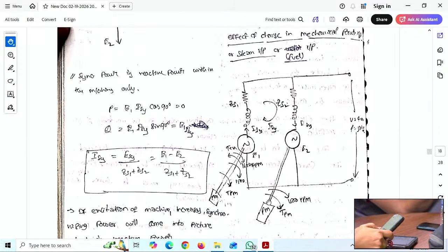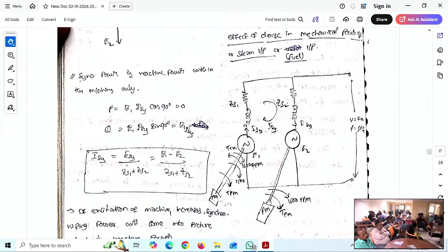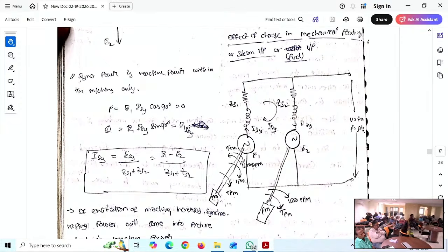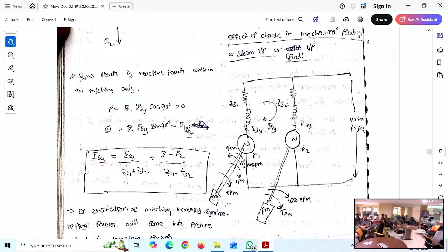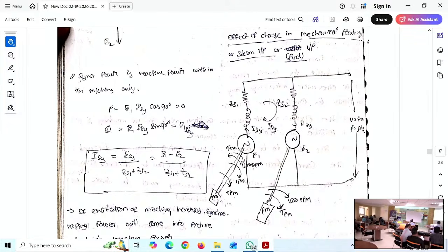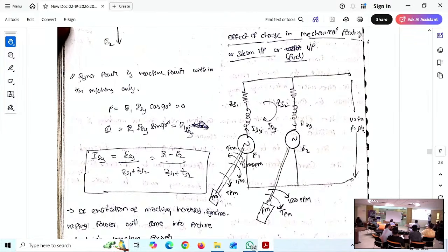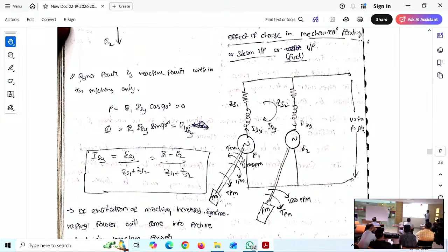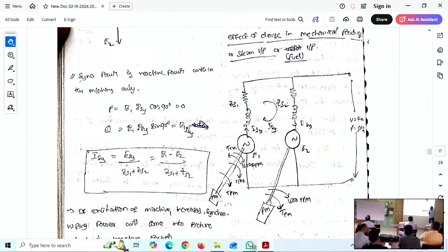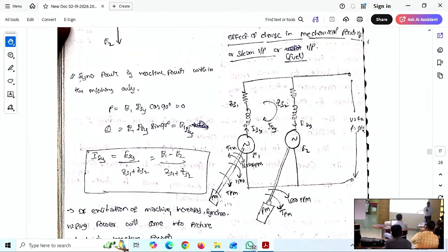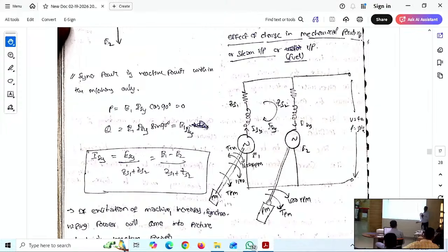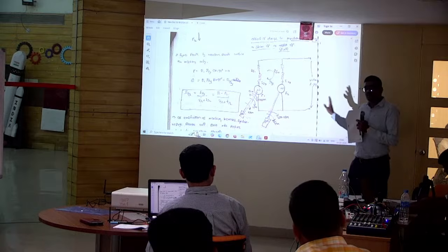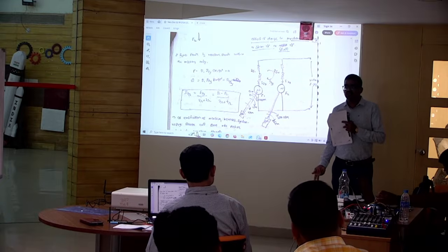This we understood, I think. In the first case, when prime mover input is constant, flux is changed. It remagnetizes the first machine and magnetizes the second machine, so that the new set becomes stable with increased voltage. Next case, the effect of change in mechanical power input, say steam input in a thermal station, or fuel input. Then what will change? Phase will change, and then current also flows. Magnitude is the same, but phase is different, so the voltage is different. Current starts flowing under no load.